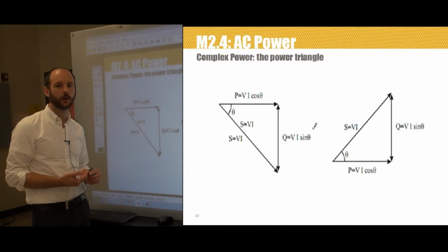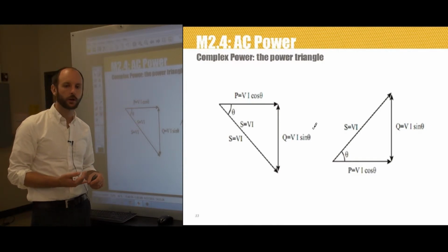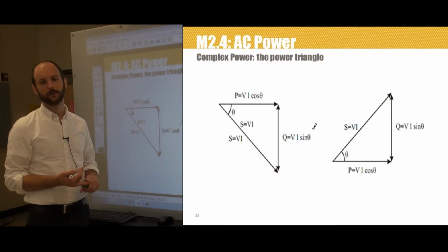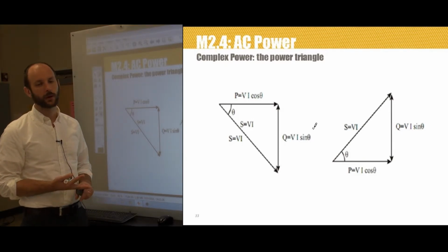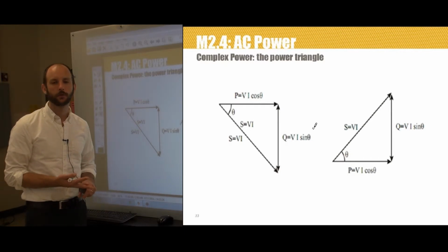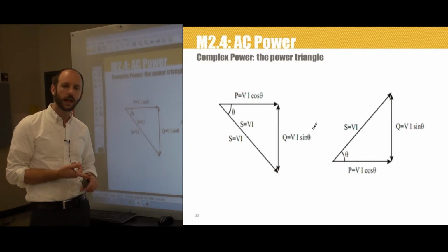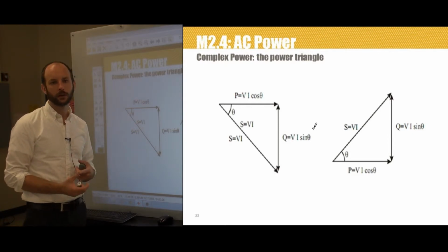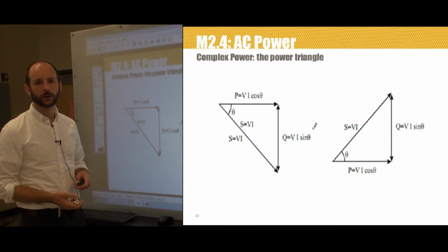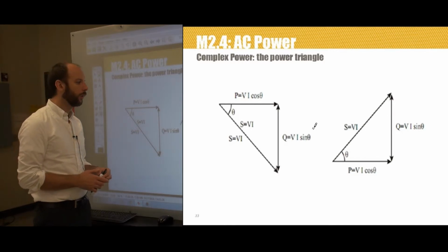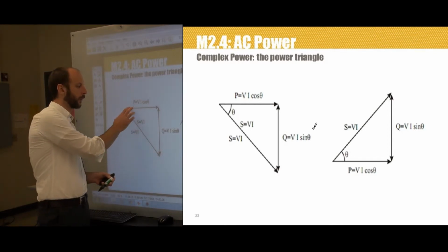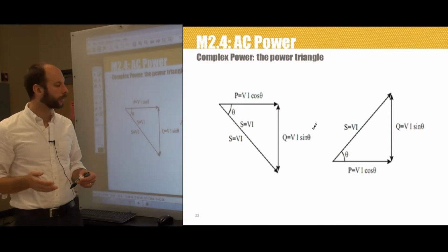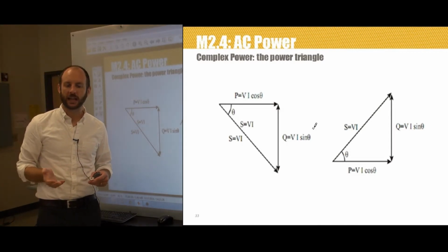Sinks of reactive power, well, a generator can alternatively be run as a reactive power sink. Inductors are the primary sink of reactive power in the system. Transformers are probably the second most common sink of reactive power. Heavily loaded transmission lines and most customer loads, which are pumps and things like that, are sinks of reactive power. Well, why do we even talk about this reactive power? Why don't we just leave it decomposed into its P and its Q components? Well, the influence of this apparent power, we really can't underestimate it.